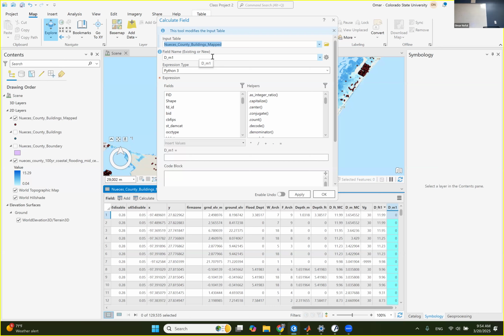Once you are done, keep looping until you finish all the buildings, then end, and give me the final shapefile. That's what the damage process is doing. So I connect this fragility with the building, read the flood depth, get the damage, write the damage for this building, continue the loop until you finish all the buildings, and then write a new shapefile with the new results.